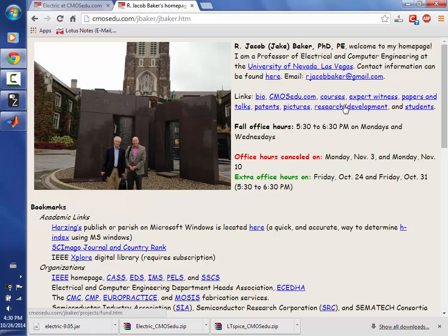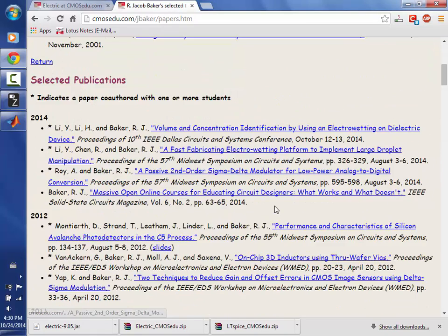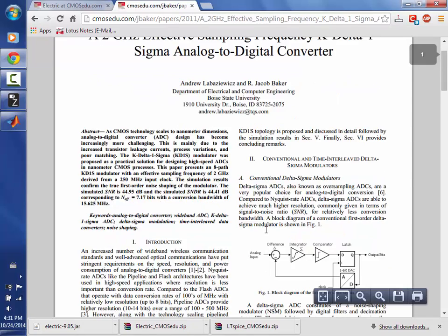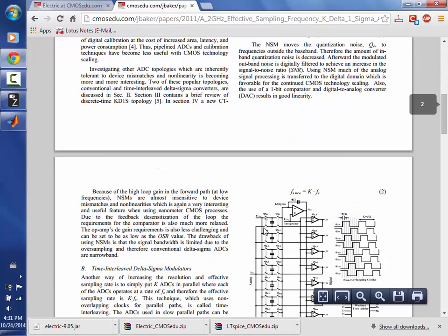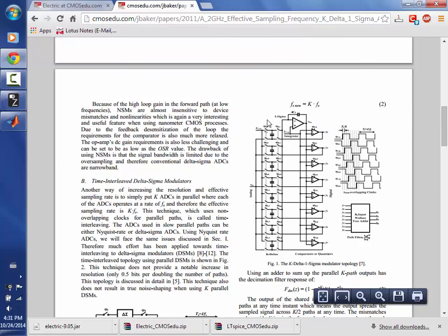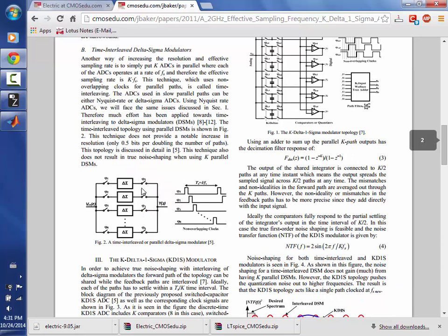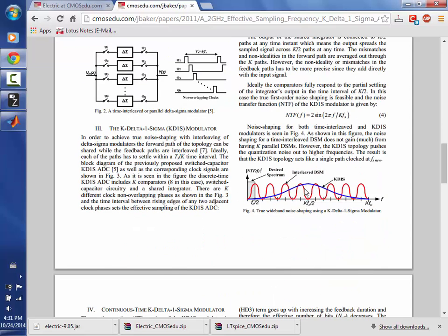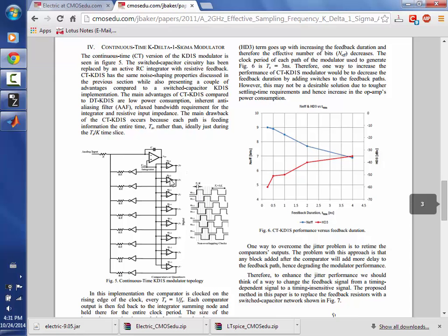I'll show you. Where is it? This one. So this is, and we'll talk about it today. Here's what's in the book, right? It's basically a K delta. It's got switch capacitors here. They'll sum up into the integrator, and you go from there. And then here's the discussion of putting delta sigmas in. Then here's the introductory discussion about wanting true noise shaping. Here's some discussion, so if you get a chance, look at this, on continuous time delta sigmas using resistors.